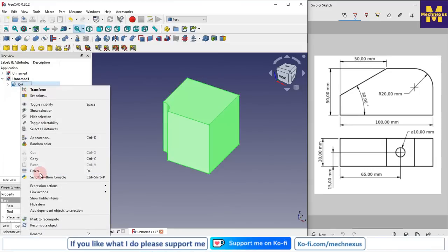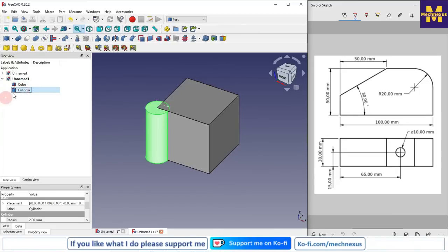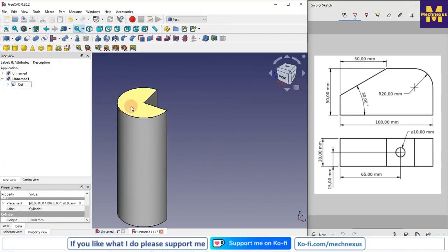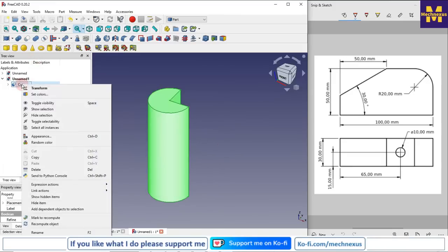But what if I select in reverse order? First I will select the cylinder and then the cube, and then if I press the cut option, you can see that now the cube has been subtracted from the cylinder. So that is how selection order is very important while performing the Boolean operation.